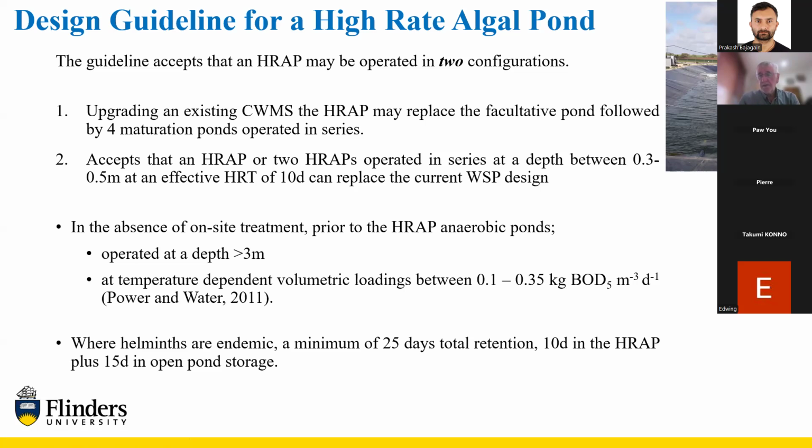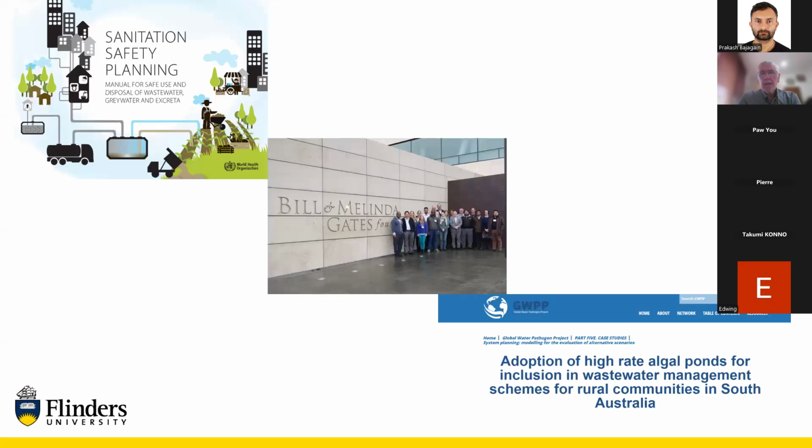And the total residence time now is 25 days, 10 days in the high rate ponds and 15 days in a storage pond. So this was quite a significant achievement, really, to get high rate ponds accepted as treatment systems. And it was recognised, our publications, we were invited to go to the Bill and Melinda Gates Foundation to attend a case study meeting where they were looking for